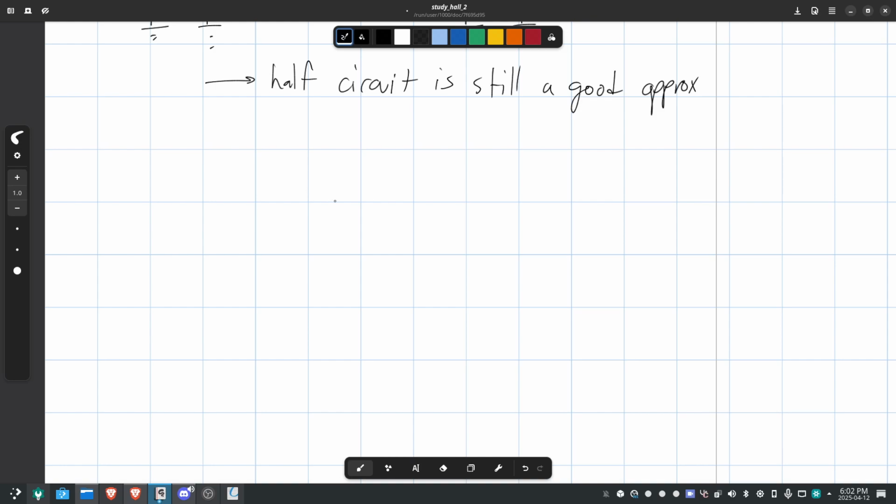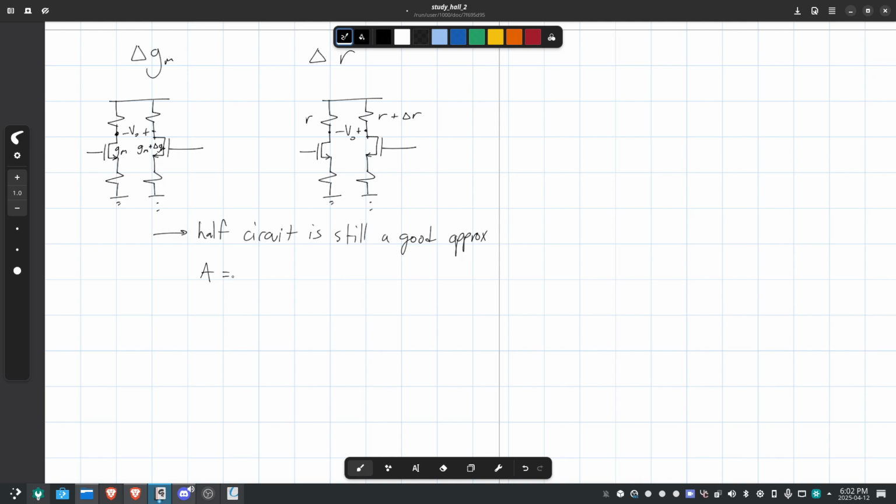So you could find the amplitude of these circuits, and we call that the common mode gain, which is just VO over VI. Again, you could solve for this. It's not something you remember, it's something you solve for. You have to rearrange the circuit, bring it all into models, and then find A_CM. Now this is going to be small, right? Because these two circuits are identical. But you will have a difference because you have this minor incorrect part.